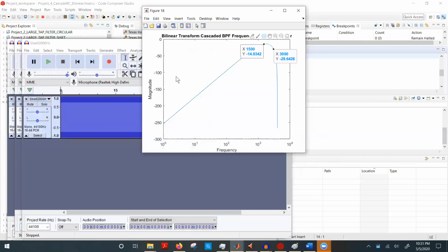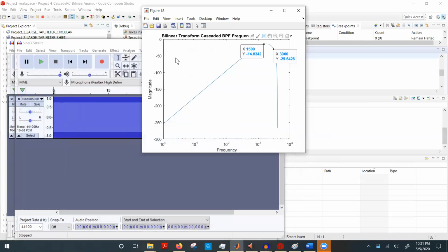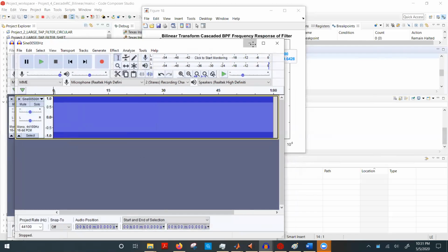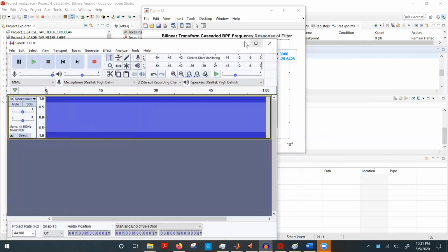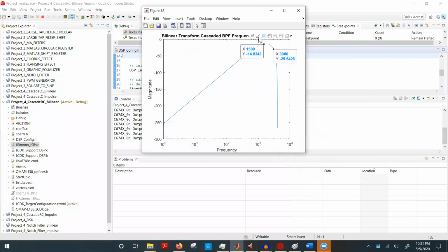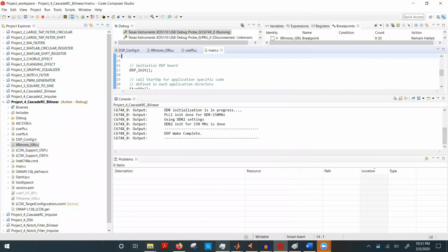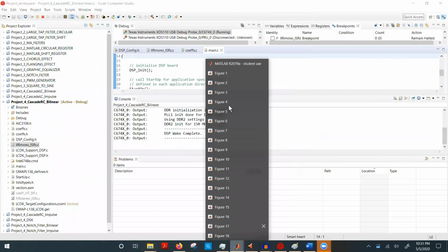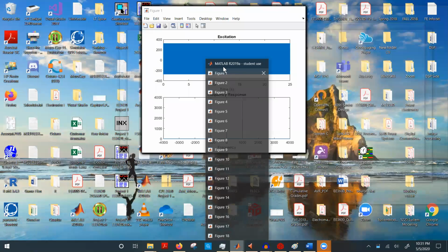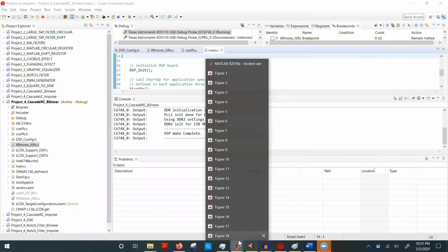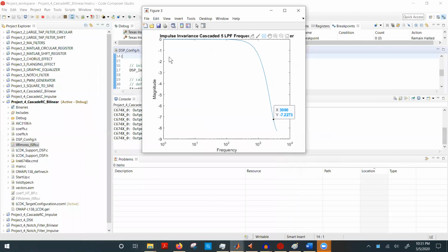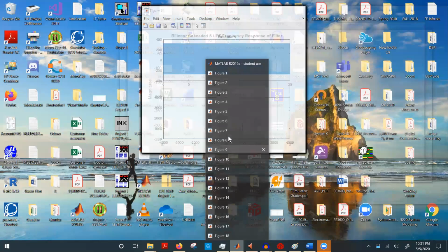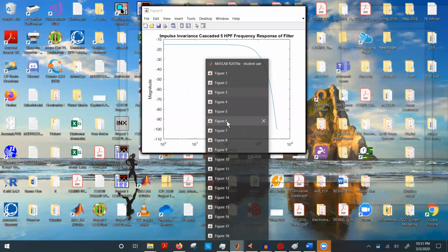So that's going to be our demonstration for the cascaded RC low pass and high pass filters to make band pass filters. The general design is correct, and the implementation is, I'm pretty sure, correct as well. The only thing that might be slightly incorrect is this inconsistency with the scaling in terms of the low pass filter. I should have looked at the other filters real quick.